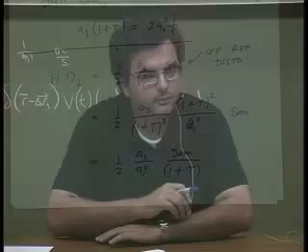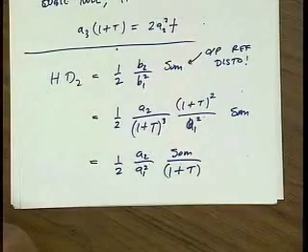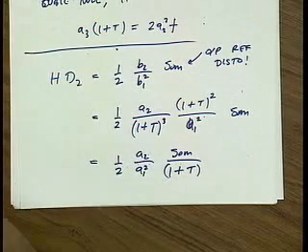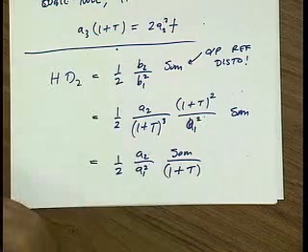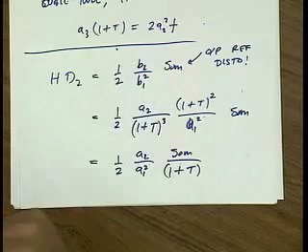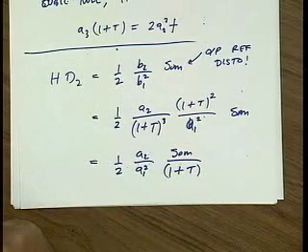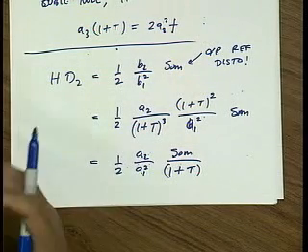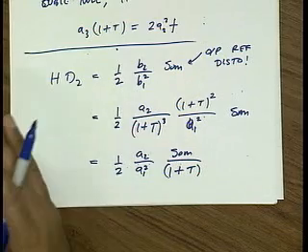Basically, we know that feedback reduces the gain of the amplifier. So because of the feedback, I'm going to get less signal at the output. So I might as well compare apples to apples. At the end of the day, I need a certain output signal. So that's why I do output referred HD3. Because if I just do input referred HD3, it's not fair.